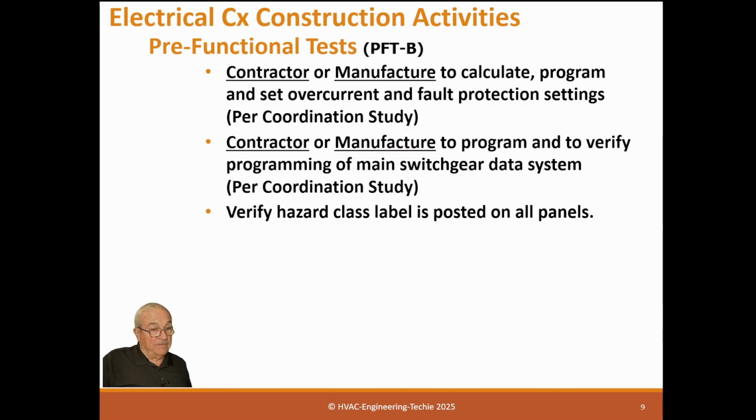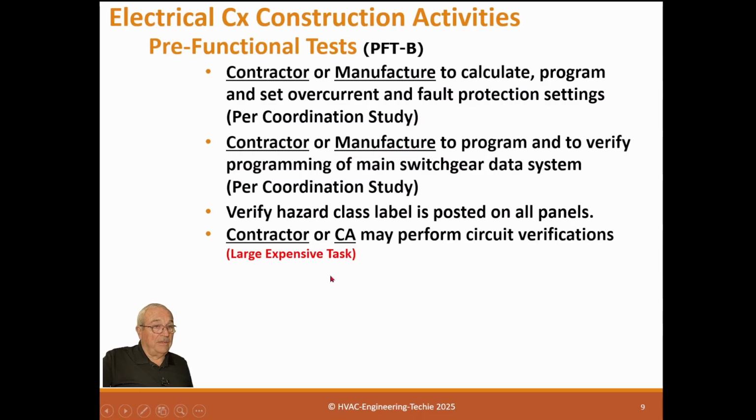emergency fire would be if there's an arc flash event. So basically, there's from 0 to 4, and 0 just needs a faceplate, and 1 is basically cotton clothing and a faceplate and gloves. 0 is gloves too, and then 3 gets bigger, and 3 is a big heavy suit. 2 is a suit, 3 is a suit, 4 can't enter it. You got 4, forget it, you're not going in the panel. You have to de-energize it to enter the panel.